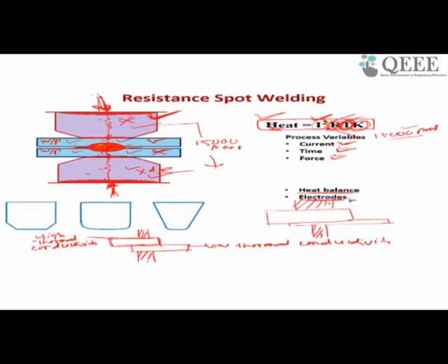That's where different electrodes come in. The first objective is that the electrode should have high conductivity. Copper has very high conductivity, so it is a suitable material, but even though copper has high electrical conductivity, its strength is very low. So from the electrical point of view it is an ideal candidate, but from the strength point of view it is not. Steel has very high strength, so it satisfies the second requirement, but steel has low electrical conductivity, so it is also not ideal. That's why they use copper alloys such as copper chromium alloys. By adding chromium they increase the strength of the copper, with only a little decrease in electrical conductivity. So copper chromium alloy gives very good electrical conductivity and very high strength. That's why they mainly use copper chromium alloys for electrode material.